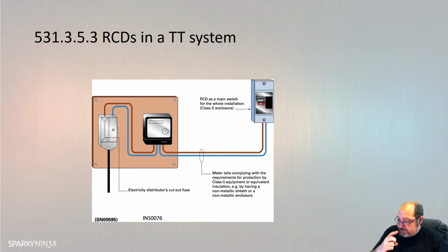In English, what this means is to determine a value of RCD rating, I delta, we need to measure the value of RA, and there's a magic number that's not illustrated on this page. We've seen a formula before, back in part 4, Ohm's law, and we need to remember that when we touch on RCDs and TT systems, we're verifying that the person in the location is exposed to the values of voltage, and so we make sure that the potential voltages there do not exceed what we think is the value of voltage that could harm persons.